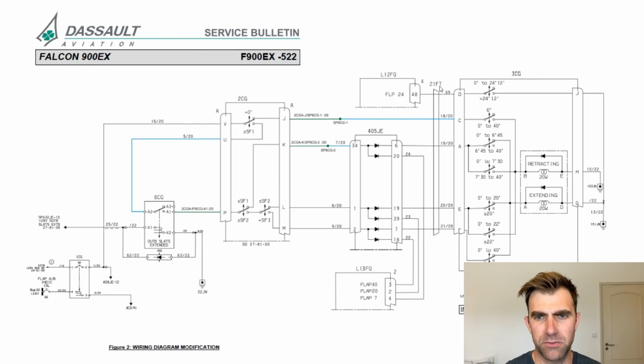FT stands for feed through, so feed through number 21. There should be a label on the bulkhead where this feed through is located to show you the location of the wiring. So that's another thing you can watch out for, if there are no letters or numbers on what appears to be a connector, so that doesn't get confused.